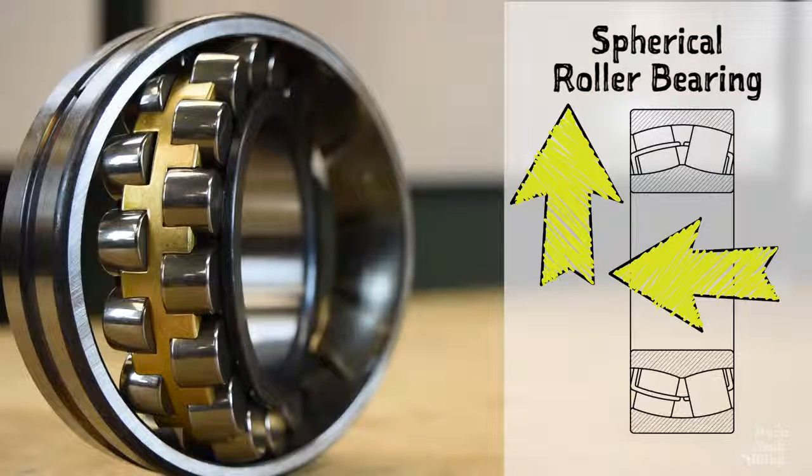The spherical roller bearing is designed with barrel-shaped rollers that ride in a curved outer race. Their heavy-duty double-row construction makes these bearings capable of supporting the greatest amount of both radial and axial load, and they can handle a good deal of shock or impact load as well. The inner race and rollers are free to pivot inside the outer race, so these bearings can handle considerable misalignment. However, this aspect of their design also gives them low accuracy when compared with other bearing types.